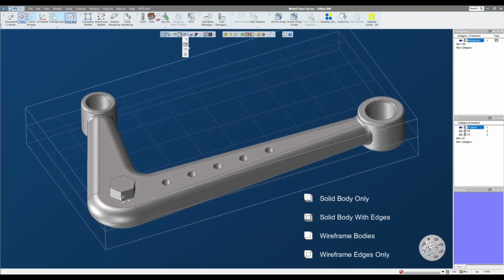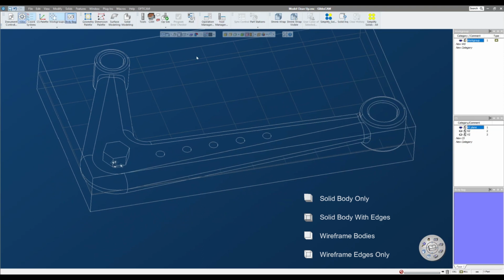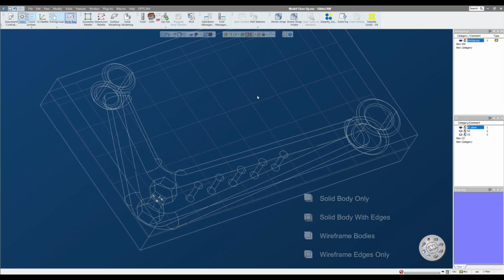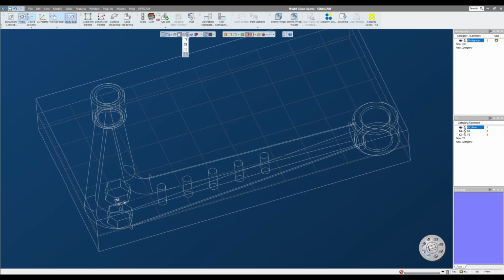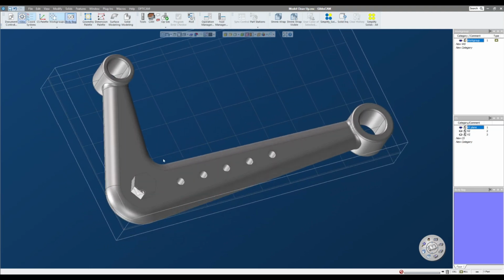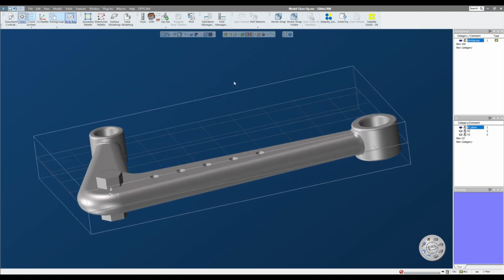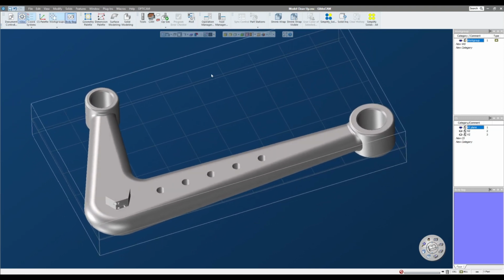That's good to give yourself visibility, and you can get a little bit more detail out of any model that you have imported. The lesser 2 used visibility modes are render hidden edges, which gives you a wireframe, and then there's a transparent wireframe. These last 2 modes aren't used very often. I'm typically a fan of seeing all of my edges, but most people will use this mode, which makes everything appear a little bit smoother.